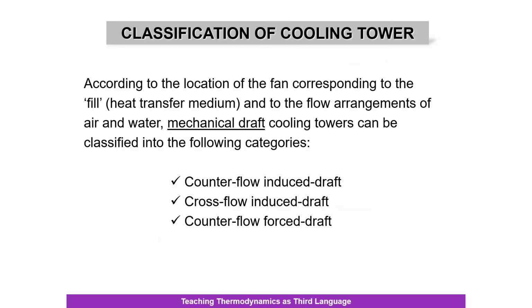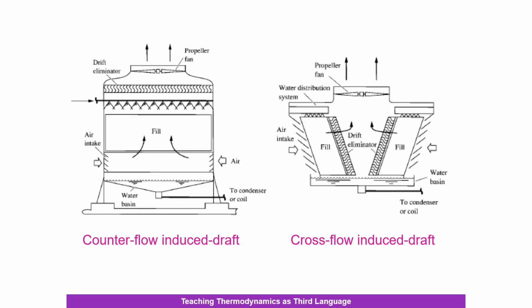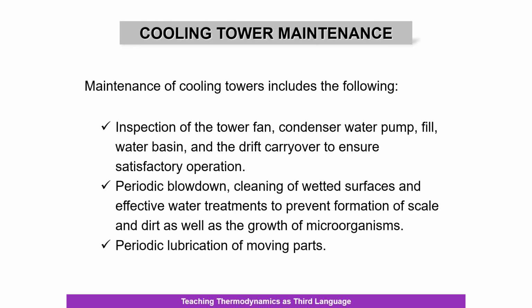We can also classify cooling towers according to different categories here. You can have counterflow induced draft cooling tower, cross flow induced draft cooling tower, and also counterflow forced draft. These are some of the diagrams. So this diagram shows the counterflow induced draft cooling tower, and here you have the cross flow induced draft cooling tower.